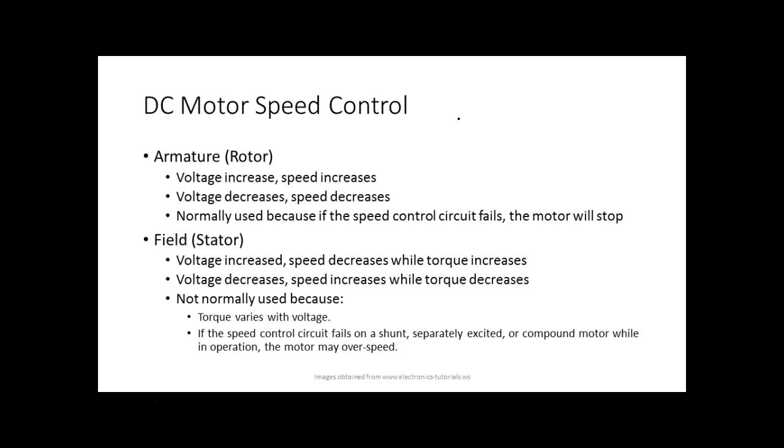Field: if we increase the voltage to the field, which increases the current, y'all understand that, it decreases the speed while torque increases. Voltage decreases, speed increases while torque decreases. Not normally used.